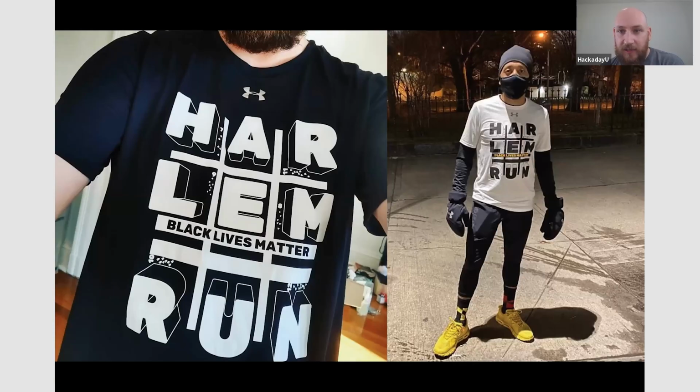And then here's another example that I did for a t-shirt where you can do any font in Rhino, drag in custom fonts. So this is Rubik from the Google Fonts collection. And if you explode a font, it turns to curves, so now they're just NURBS curves. And then I just extruded those curves, drew some roads between, and messed around with the camera settings that I'm going to talk about later to create this perspective view with a wide angle lens.